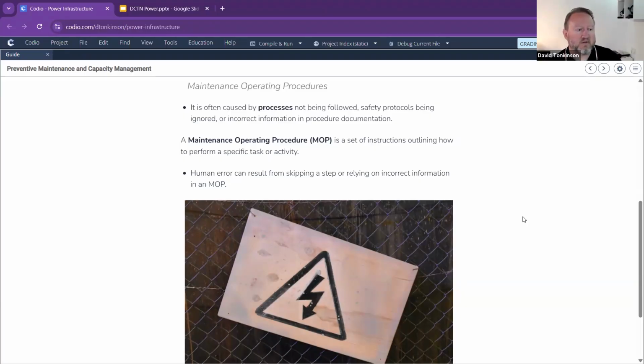Kadir says, why is it important to regularly test standby generators under both load and non-load conditions? You like to do it under load because it's live. You are not only testing the power generators, you are testing the connection that goes back from the generators and feeds into your transformers and into your data center. If you do it non-live, then potentially there could be a fault in that electrical cabling between your generator and your power units. And that's what you're trying to do.